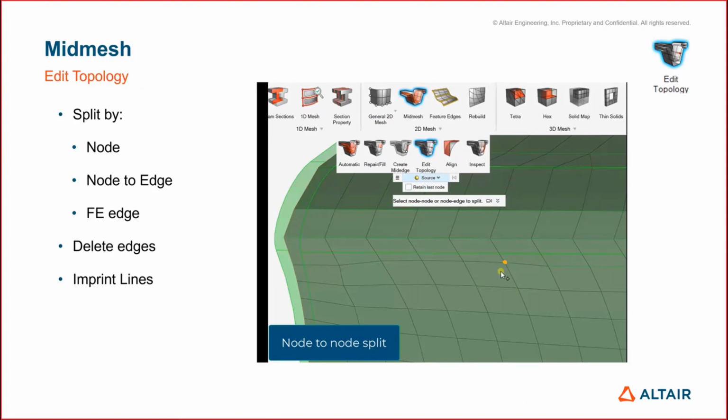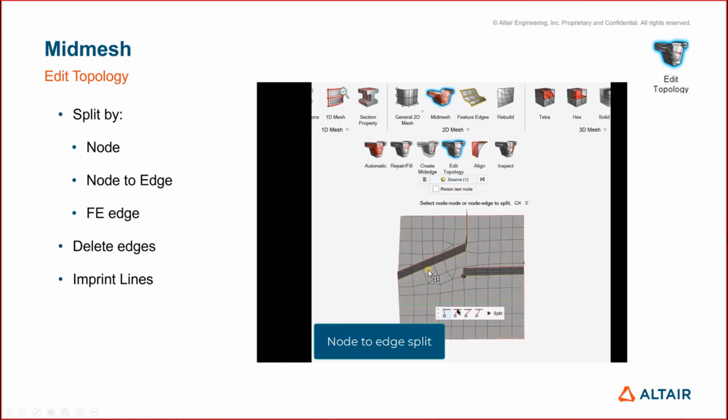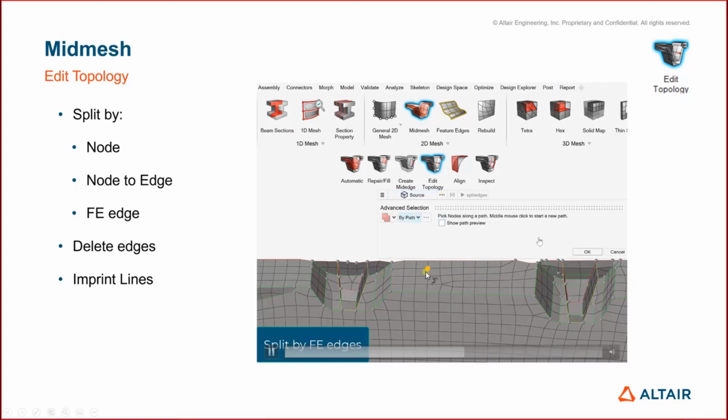The edit topology tools have also been enhanced. Working on edit topology is just like working on CAD. If you do a node to node split, you would see the surface that has been created here. Here we are doing a node to a surface edge split, which is the shortest distance. The next item goes to a node to a selected point, and then you would do a radial or mixed split. During all of this, you see these edges and there are no more 1Ds interfering.